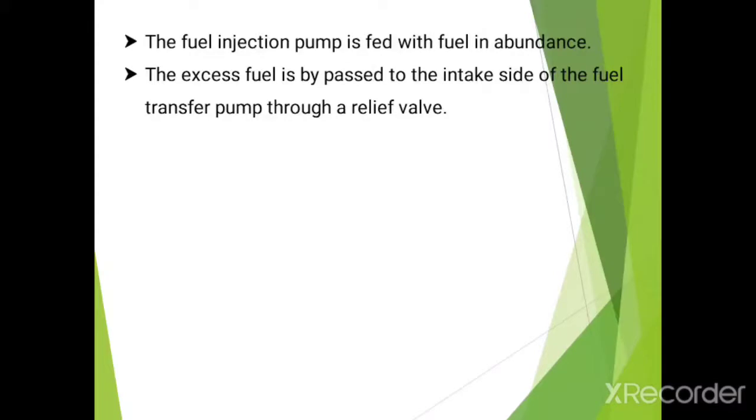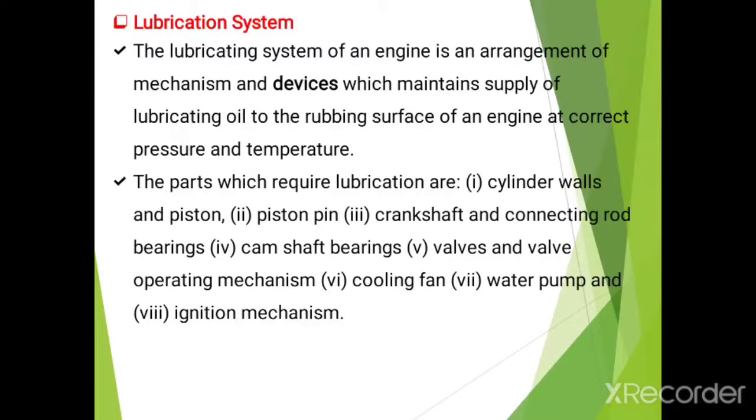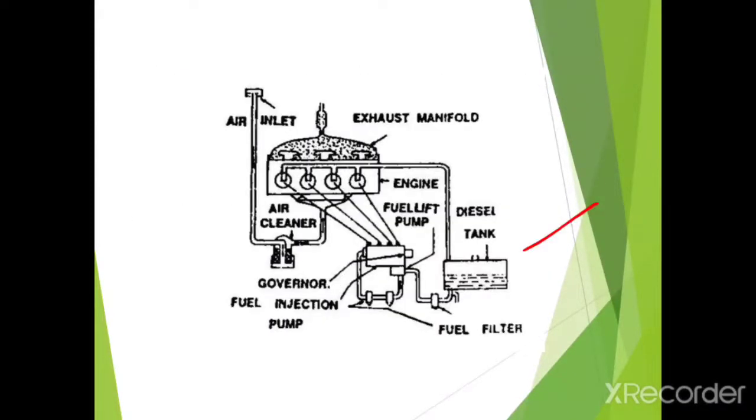Then the fuel injection pump is fed with fuel in abundance, so the excess fuel is bypassed to the intake side of the fuel transfer pump through a relief valve. So the excess fuel is transferred towards the diesel tank through the relief valve.